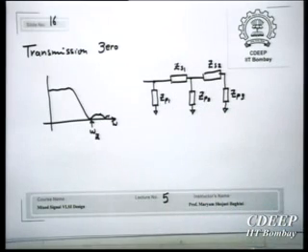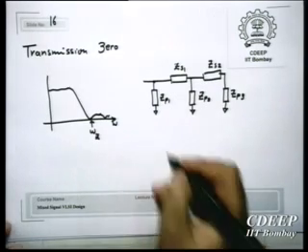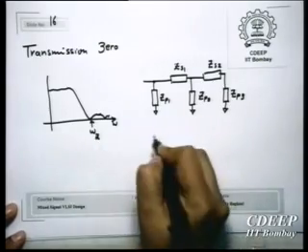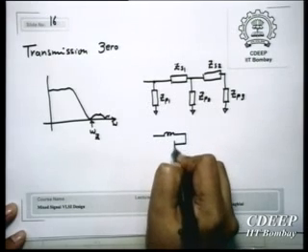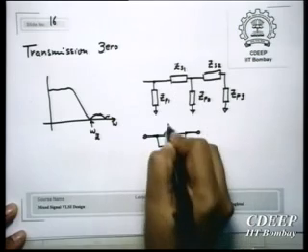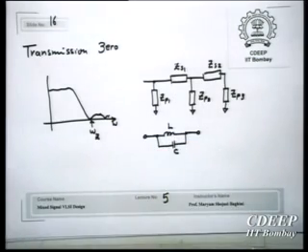It's enough to cut the series impedance, and to cut the series impedance means to make it infinite. Therefore, the best way to make an infinite impedance at some imaginary frequency is to use a parallel LC, which will resonate at that frequency. Therefore, this will be the transmission zero, simple.